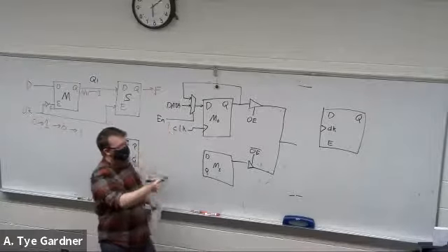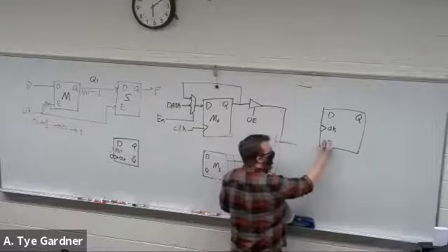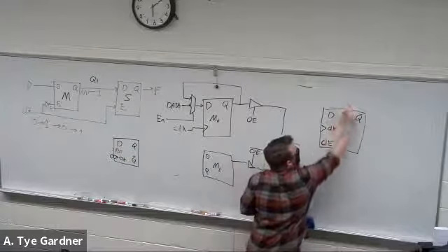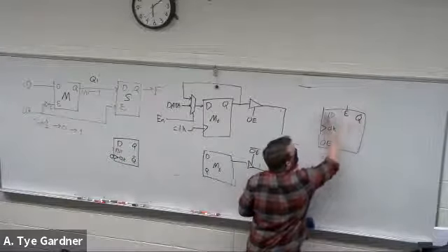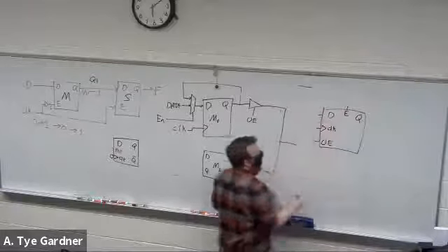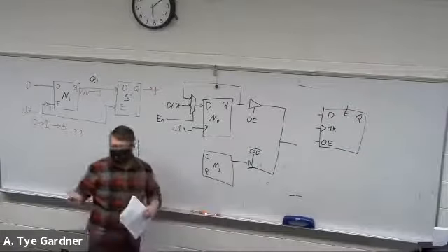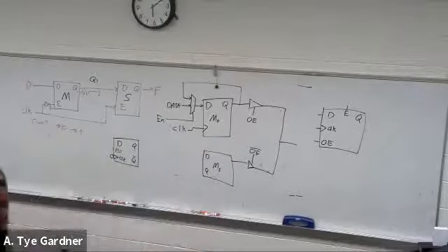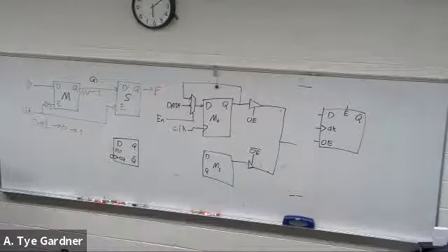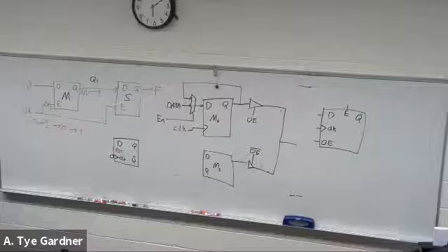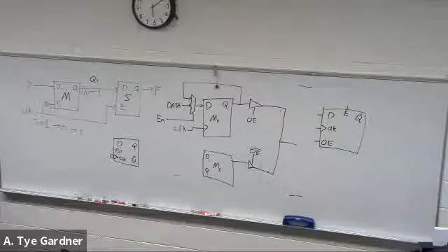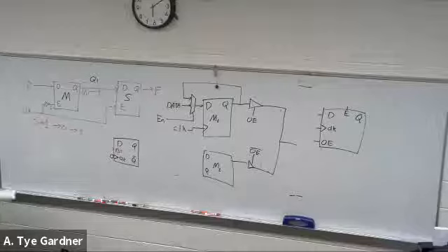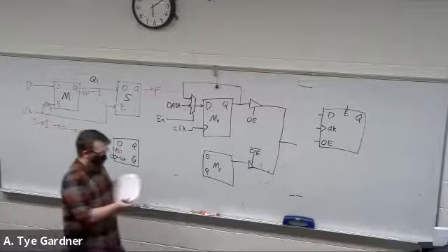You might also see it like that with both an output enable and an input enable, right? Each of those options makes more and more complicated circuits to build. But it's just a couple extra inputs on a gate, so a couple extra transistors. It doesn't cost a lot to do, and it adds quite a bit of functionality.